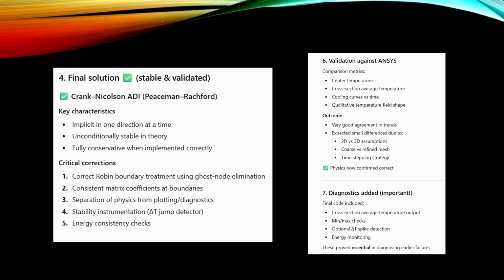After running my first simulations with explicit code, I developed my Python code so that it now uses the implicit time-stepping method. I also ran some simulations with Ansys Fluent, and I compared the results between this Python code and the Ansys simulations, and some modifications were made based on those comparisons. Here you can see some details of what was done.